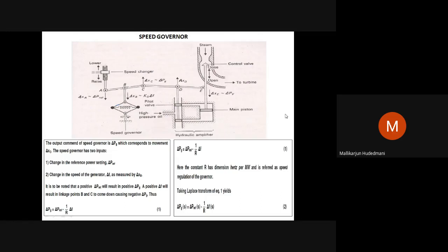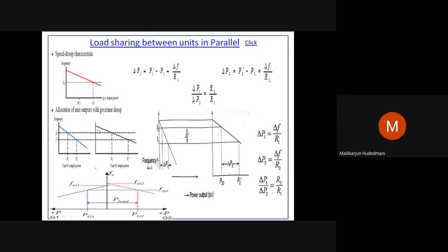As the load on the generator is increasing, what is my observation? The RPM of this feedback will lower. This will reduce. If the RPM falls down, then it has to open the valve so that more fuel will go. So this way, it has to open. How much it has to open is the relationship of the governing mechanism by droop nature.